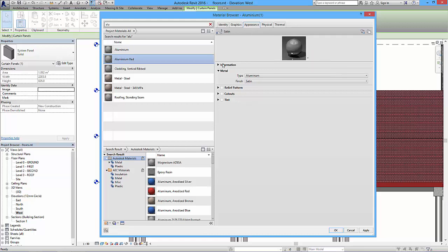And so to update that color option, that's another story, but it's to do with this thing. It looks like a pen nib upside down, but it's actually a hand holding out, and this is the sharing hand. If it's got an asset that's shared with other things, then it tells you how many times it's shared. So it's shared with 3 different things, so you end up having to use this option to duplicate the asset in this aluminium red. Then it's not sharing with anything, and then I can update this to something else.